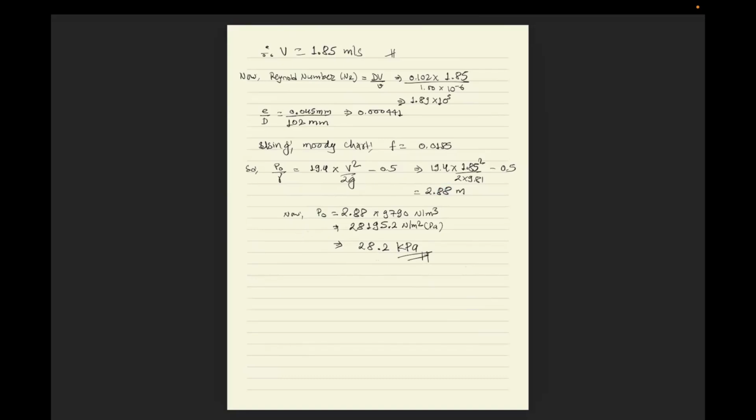So what happens if the applied pressure is less than 28.2 kPa? The answer: the pressure at point 5 becomes negative and air might be drawn into the system through small leaks or cavitation could occur.